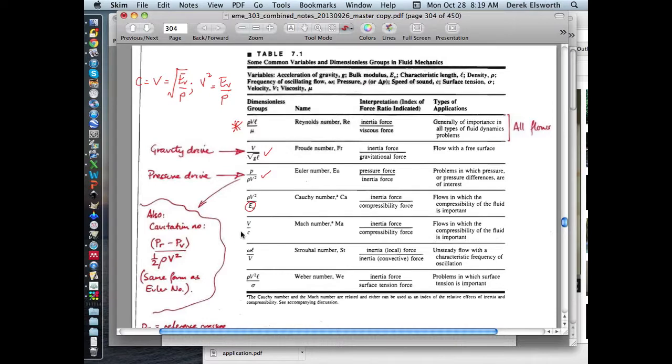So commercial airliners go less than the speed of sound, and that's because if you go faster than the speed of sound, you physically can't dissipate all the energy that you're generating by pushing yourself through air, because the energy can only get away from you at the speed of sound. If you think about it, a plane is here, this is the nose of your plane.